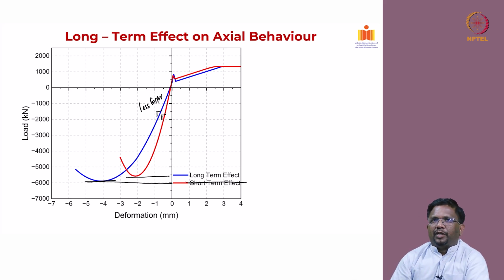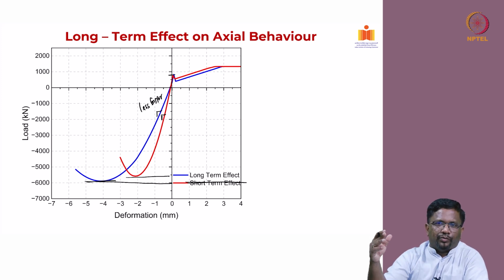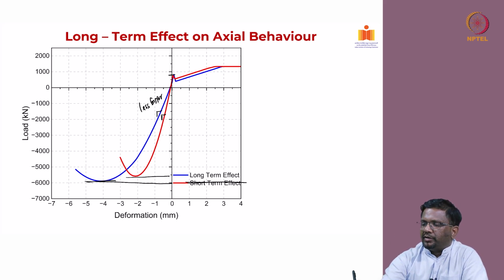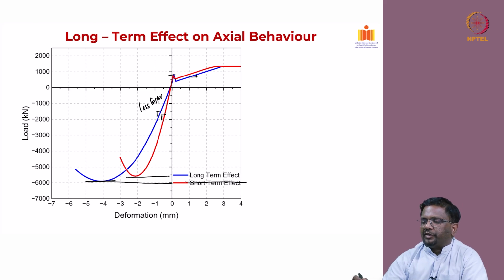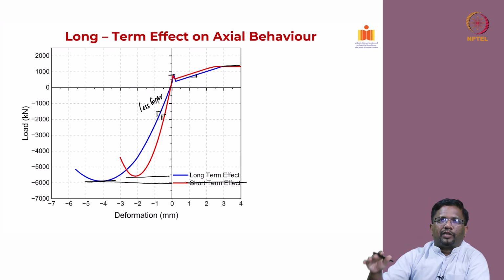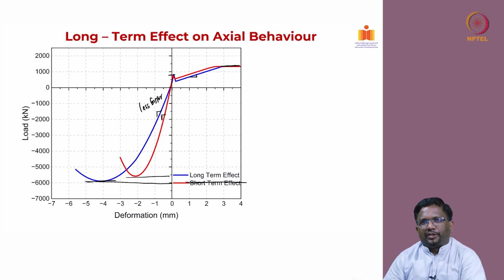what we have considered. But there is a marginal increase in your cracking load if you plug in all your values and use the same formulation for calculating the entire load deformation. And this stiffness also has a reduction, okay. Again this is the slope, okay. And you see here, this is only the steel stiffness, so a small reduction is there, and there is no change in your ultimate strength, because both the blue curve and the red curve almost reach the same capacity in tension.